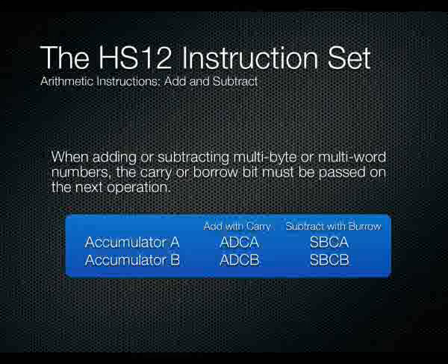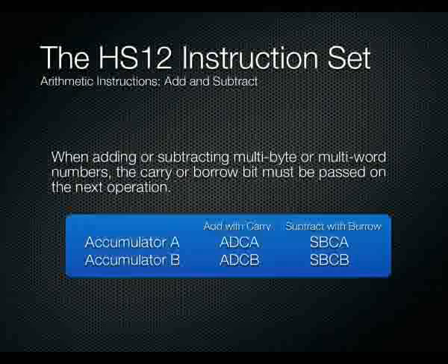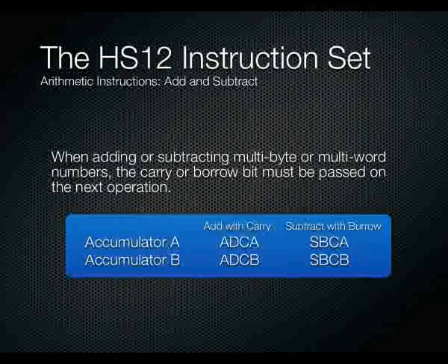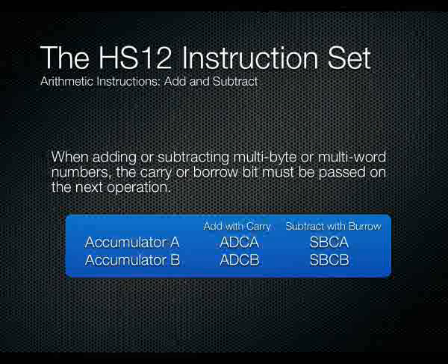So we have a series of instructions which will do an add with carry. Not only will it add the two numbers together, but it will also add in any value in the carry bit in the condition code register.